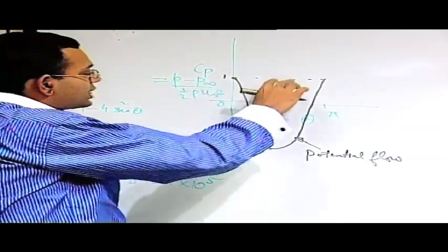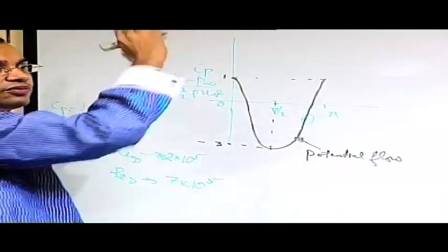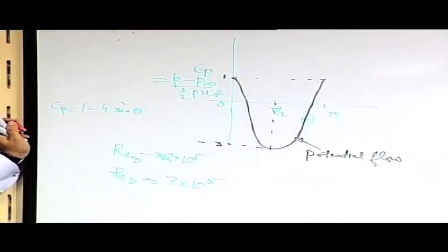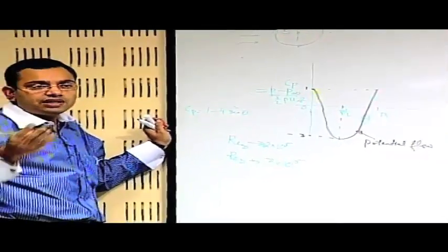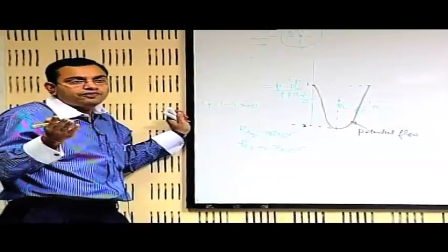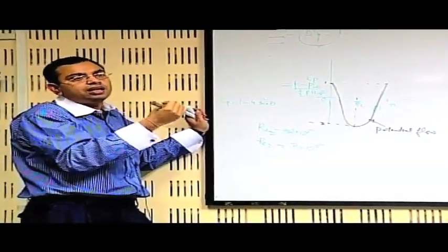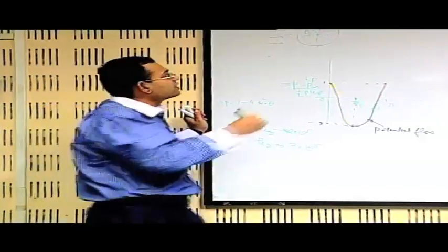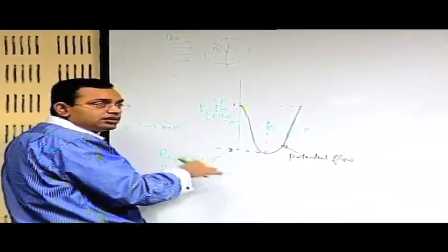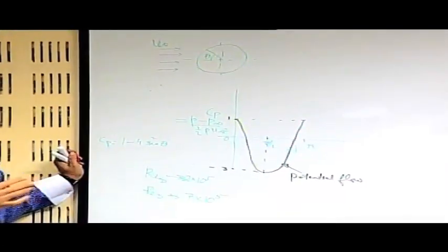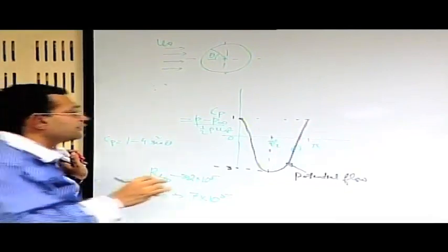So we expect usually that the separation will be there in the region where the adverse pressure gradient is felt. In reality, in the region where there is an adverse pressure gradient, there occurs a backflow, and the effect of the backflow is propagated even a bit in the upstream direction, so that the separation in the practical case for a flow of this Reynolds number regime occurs at roughly theta equal to 82 degree, that is the practical observation.